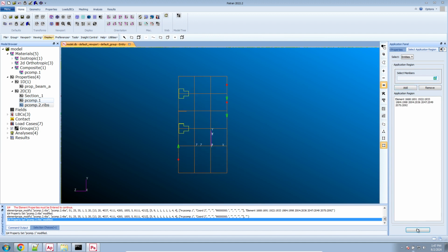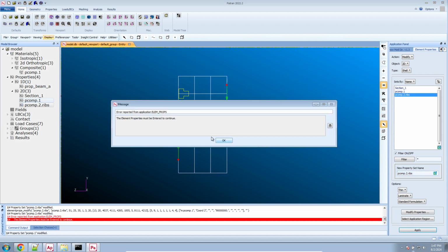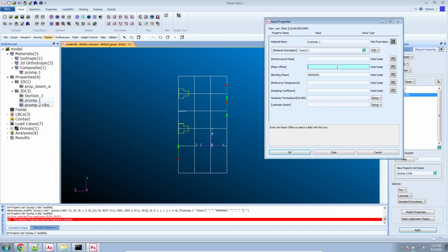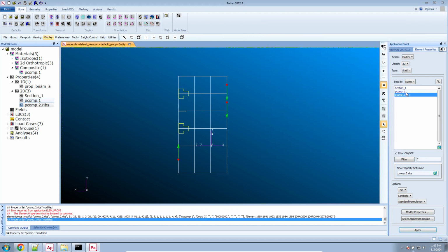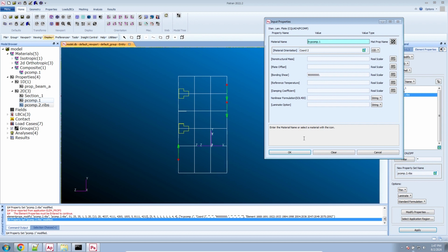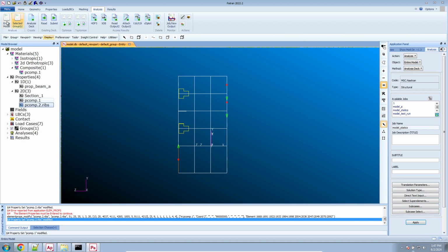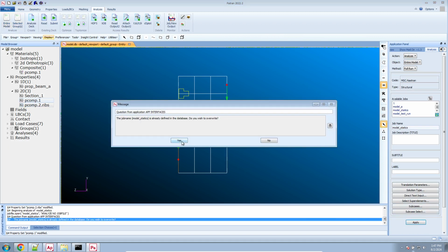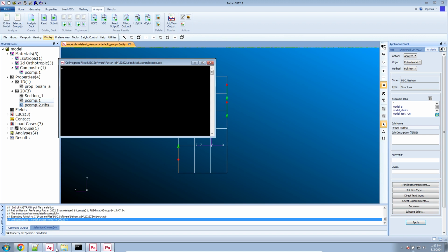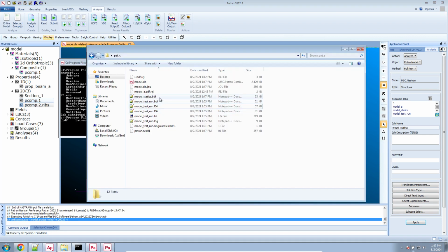So let me do this again. Click OK, click Apply. And then here, let me open this dialog again, click OK, then click Apply. Now, again, let me go ahead and look at the elements. Okay, that looks good. What about here? Okay, that looks good. Click here. Okay, that looks good. Click Analysis, Entire Model. Now click Apply. Now we can perform the statics analysis with 2 load cases. And so let's go ahead and look at the, how do I say, the F06 file.